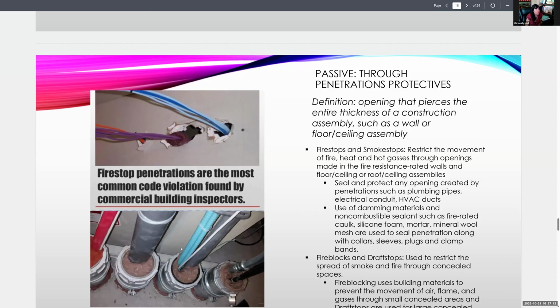So a fire stop or smoke stop, this is a band, and they literally pour in a putty in there, and it completely seals it shut. So when we're talking about these fire stops, these are things that we use to stop the fire. Usually they're in some kind of collar, or a threading, and you're able to literally seal that whole thing off so the fire does not spread in here. Very expensive, and it takes a lot of time.